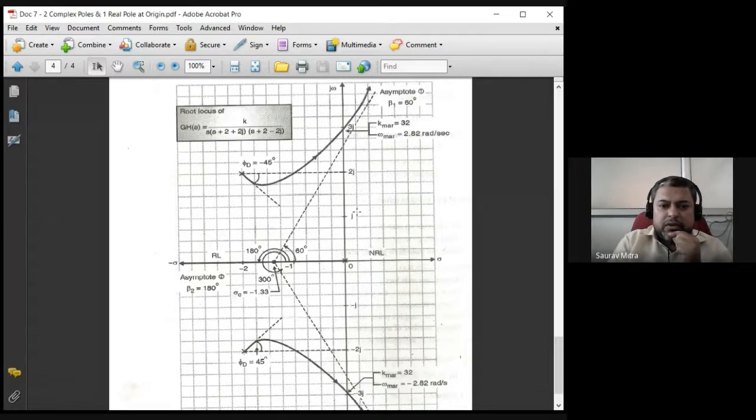Minus 45 degree means we always count from the positive side of x. So if this is the point, you have to draw an angle of minus 45 degree. For that, first, whenever I give you a point, now I'm entering something which is pure common sense, but students are to be told about that. If I ask you to draw an angle of 45 degree from here, the first thing you have to do is, from this point, draw a line to the right side. Whenever I ask you to draw an angle from any point, first, starting from that point, draw a line to the right side.